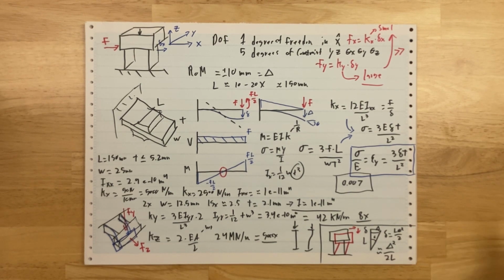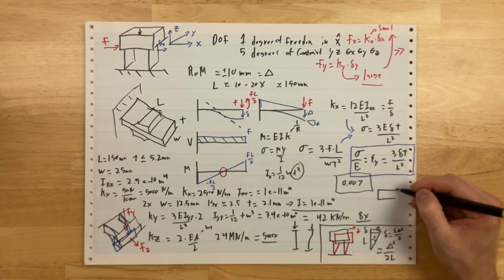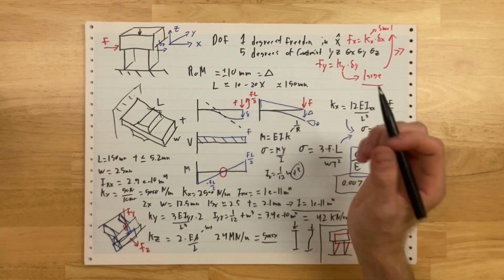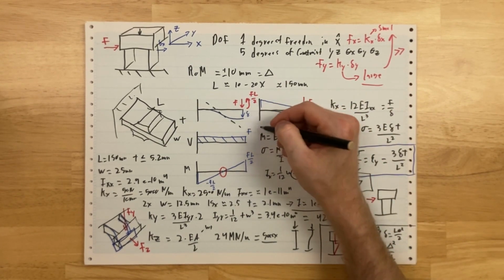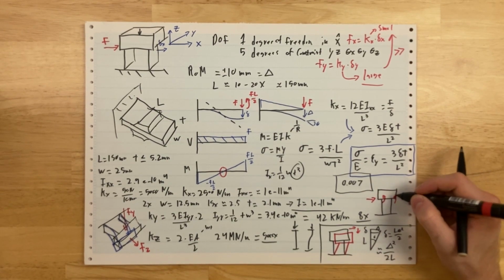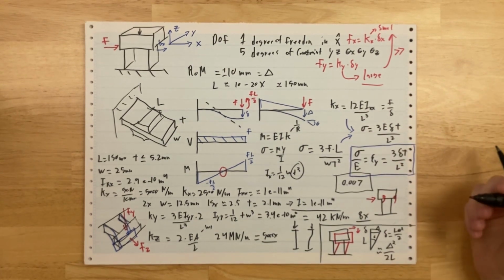There's one last issue, which, again, running out of space to describe, but when you push on a parallelogram flexure, you'll find that, we talked about this moment here. There's a moment required to keep that beam from rotating. Those moments go into this upper bar. So if those moments are going into the upper bar, shouldn't that upper bar be like spinning and rotating around? How is it balanced out?